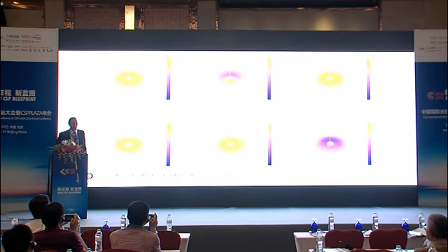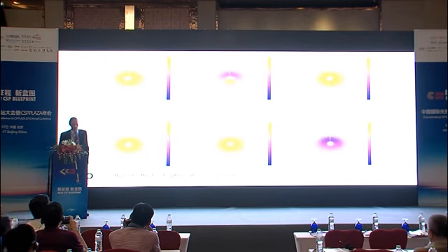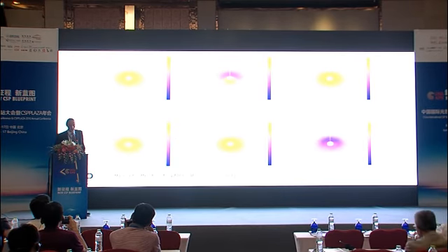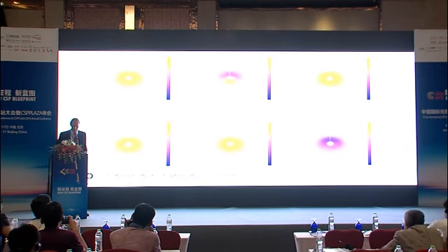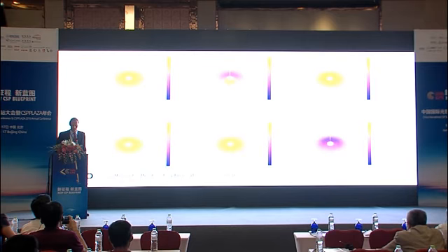So summing all of that up, just a little bit of what is optimized and what the individual effects are. It's difficult to read, but the top left one, that's the spillage. That's the one which is related to the technology and how accurate the heliostat is, but also to the distance. The biggest loss, you can see it on the color itself, is actually the cosine efficiency. I'm sorry, these pictures are actually done for the southern hemisphere, so you have to think the other way around now. Here the southern field is more efficient in this case, and the north field becomes less efficient, so that's why the colors are darker here.